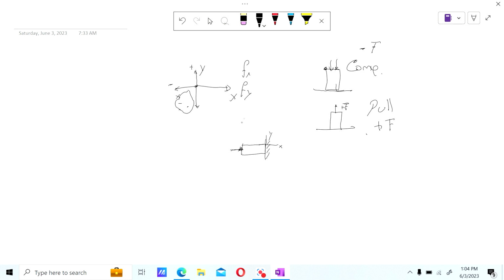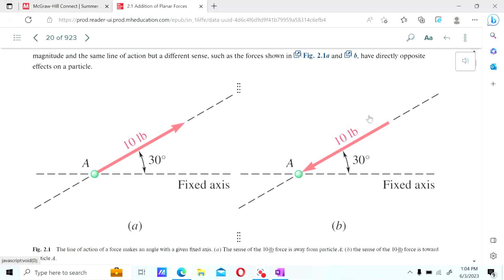For now, I just want to differentiate that you can have stretching and pulling, and the vector itself is with respect to the coordinate system. Later, when we talk about the whole system, then we have to analyze if the system is carrying positive or negative forces. Positive forces will be pulling, negative forces will be compressing, or stressing in a compression fashion. So in this case, this is a single vector, so it's negative because it's going in the negative direction, on the left hand side of the screen.